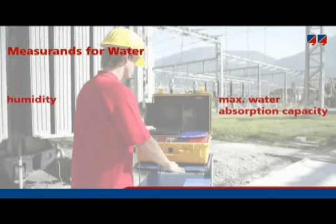Another very common example is the air. What would be expected if air has 100% relative humidity? 100% relative humidity actually creates fog. As long as the water vapor is dissolved as a gas, a nice clear day will be the result. But if the water forms droplets, fog is created. The effect is similar with oil. So, to reiterate, water saturation is humidity relative to maximum water absorption capacity.